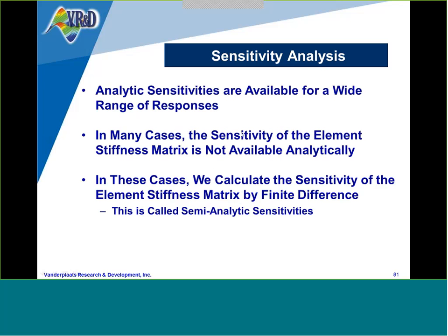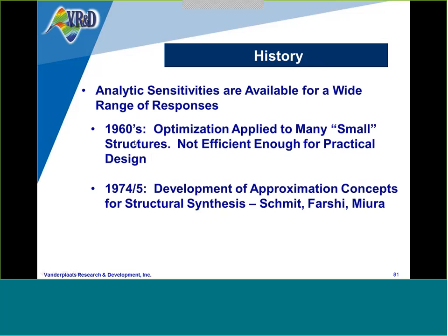These are available for a very wide range of responses. In some cases, we can't do it. We can't calculate the sensitivity of the element stiffness matrix analytically. In those cases, we use what's called semi-analytic sensitivities. That term was created by the people at General Motors Research Labs in about 1980.